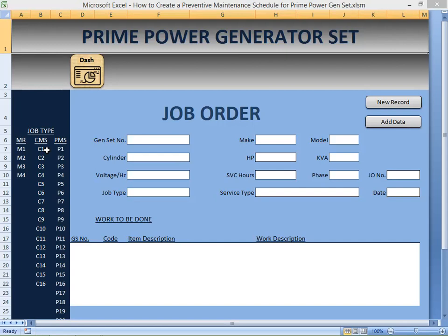Okay. So management will also be able to put a scheduled preventive maintenance plan in place. That's very important. Planning and scheduling program. Management will plan for the financial budget. Very important, because when you're doing a preventive maintenance program, you should have inventory stock, like spare parts, like oil filters, fuel filters, air filters, oil, and some other things that you have to put in stock, because you're going to be doing scheduled maintenance for the next 6 months or the next 1 year.